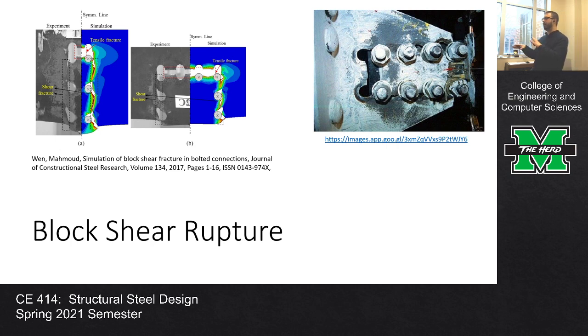If you remember, we talked about block shear last time that we were together. We didn't get into the math, but I want to get into that today and get into an example. Block shear is what happens when you have a tension member connected via a series of bolts. To be clear, this could happen with welds as well, although we're primarily going to be focusing on bolts. This is when you have a chunk of the member being ripped out.